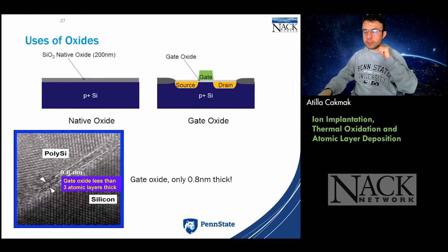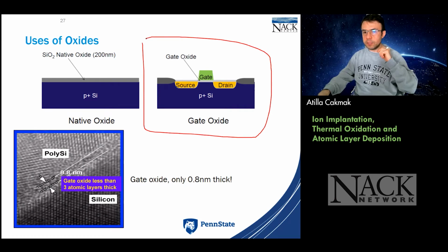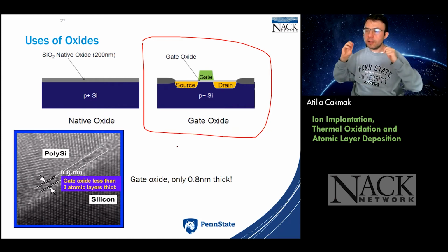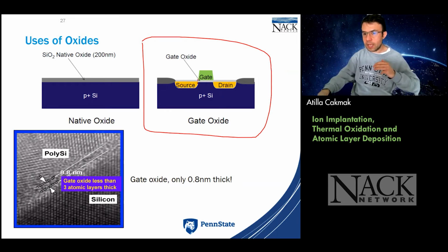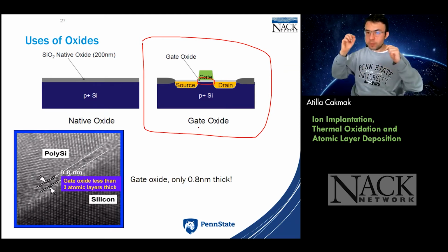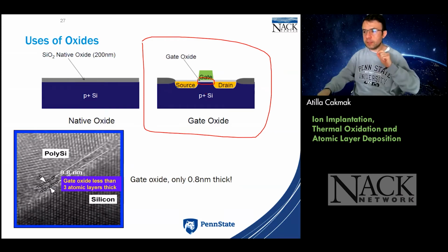Why do we really need to care about the silicon dioxide that much? Because if you look at this figure here, we use silicon dioxide every day in our lives, because for every little transistor we need some isolation. We need to say, okay, this electrode and this electrode will not be touching each other. So we need that isolation, thanks to, say, the gate oxide, which is the most important isolator, the most critical thing ever in a transistor. So this thin little oxide is extremely critical for the safety of our transistors.